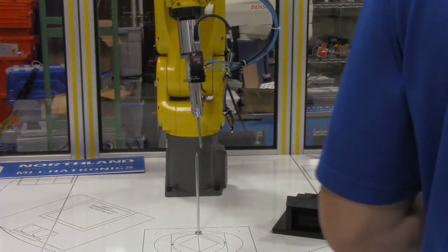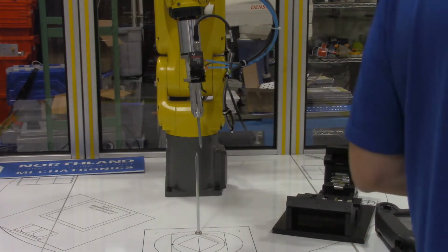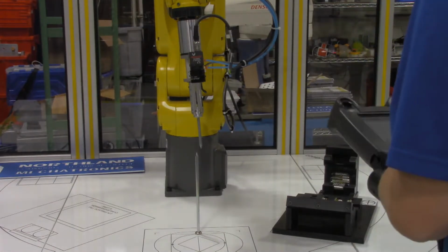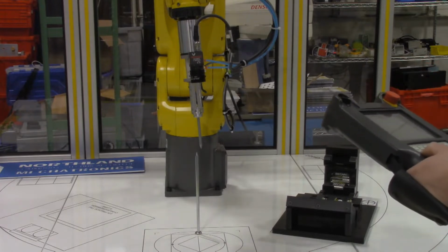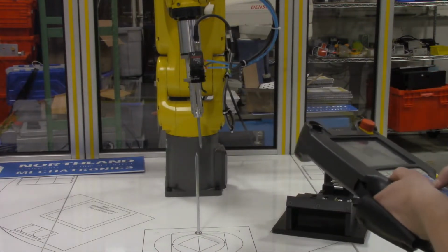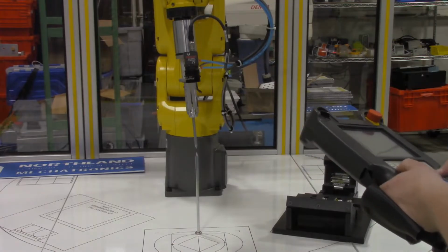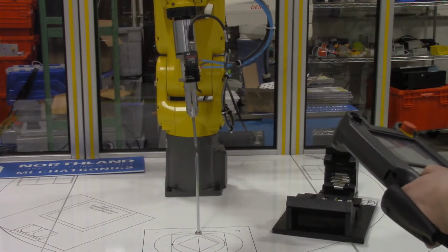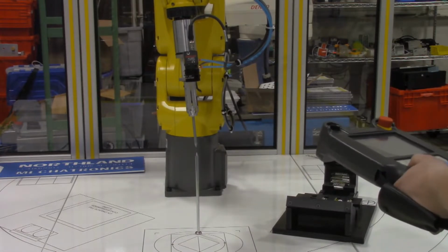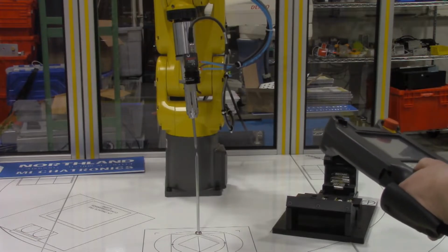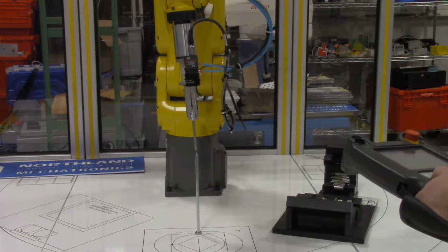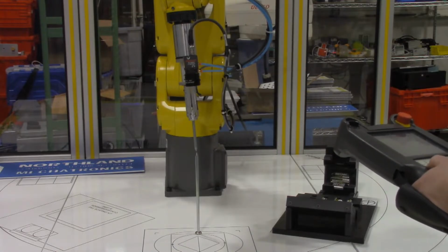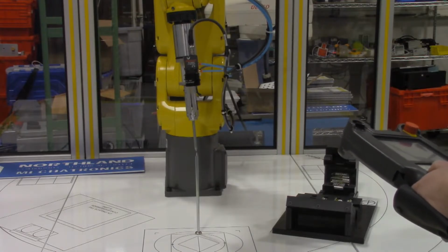So now with that set up, we should be able to jog the robot around, and it should change the way it jogs. So I'm going to once again get our XYZ set up so that those two tips, the tooling tip and then that fixed point in space for reference, are set up. And we can change the speed so that we can do this much slower.